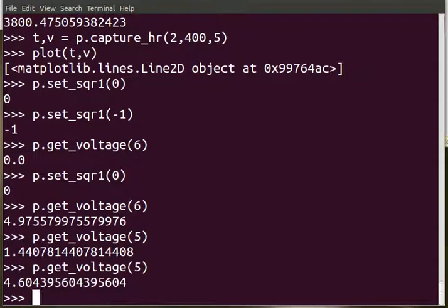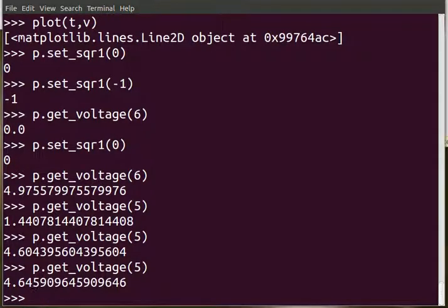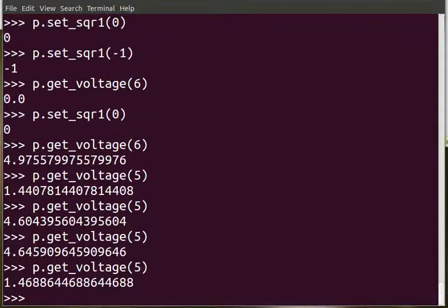That means almost all the voltage is getting dropped across the LDR. And if you again allow it to the light and make a measurement, it is low. If you put some very bright light, it will go to a very low value, because the resistance compared to that 5.1k is going very small.